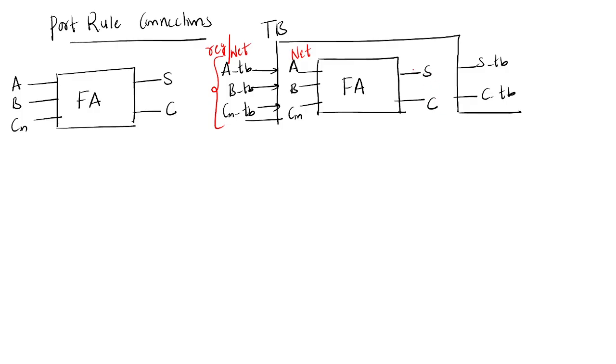Coming to the outputs of this design, it can be net or reg data type. The output for the test bench should be net data type. So these are the port rule connections.